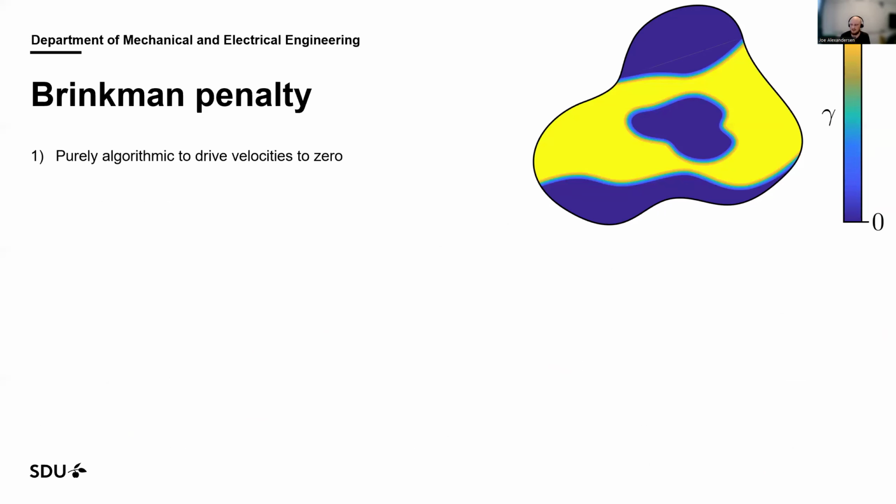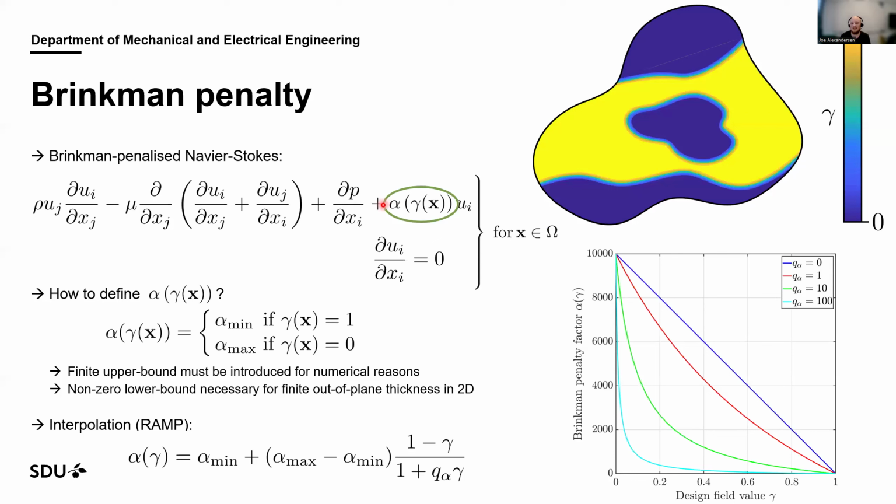So you can look at this, what we call this, the common terminology is Brinkman penalty, but as I was made aware of recently, it's not really a Brinkman equation when we have this. Actually, if this is large enough, it kind of becomes a Darcy equation, so maybe it would be more appropriate to call it Darcy penalty, but nonetheless, people call it a Brinkman penalty.